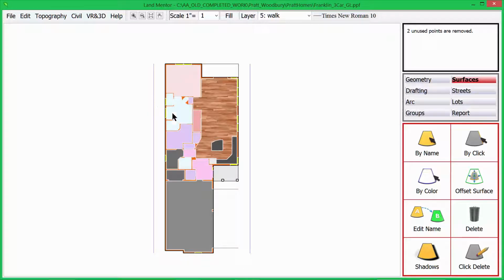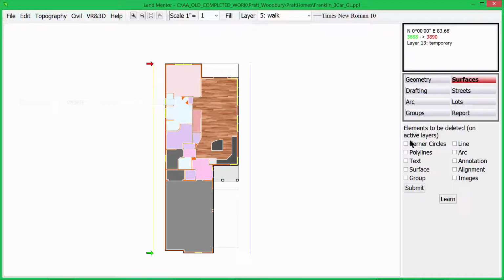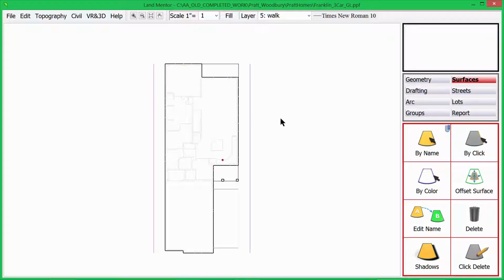This is the 2D model we use for design, and we have our side setbacks for the design phase of the neighborhood, and we have that in the site plan, and we need to prepare it the same way, the perimeter, to have the Collada file embedded in it. So what we're going to do is go into edit and then delete all elements by type, and we're going to just delete the surfaces. And now we've got no surfaces, and what we really want is this perimeter here.